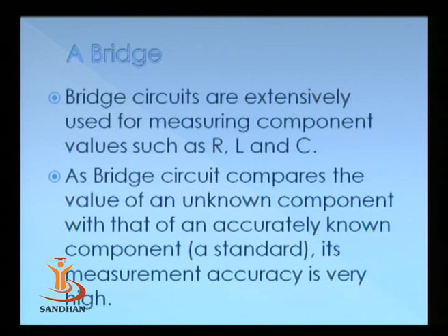Bridge circuits are extensively used for measuring component values such as R, L and C. A bridge circuit compares the value of an unknown component with that of an accurately known component, a standard value. We are using a standardized resistor so that the resistance is highly accurate and is being compared, so the measurement is also very accurate.